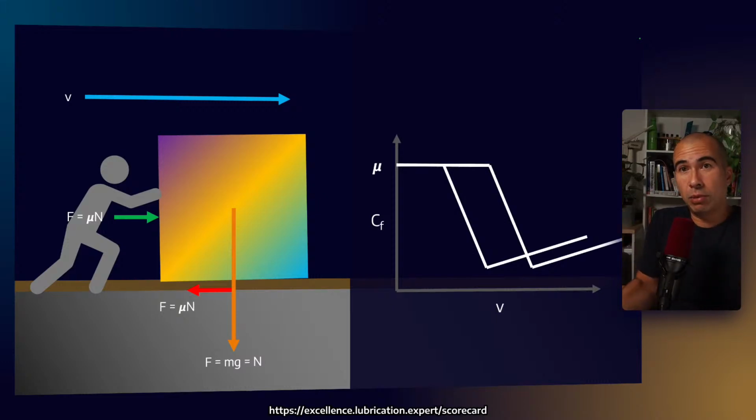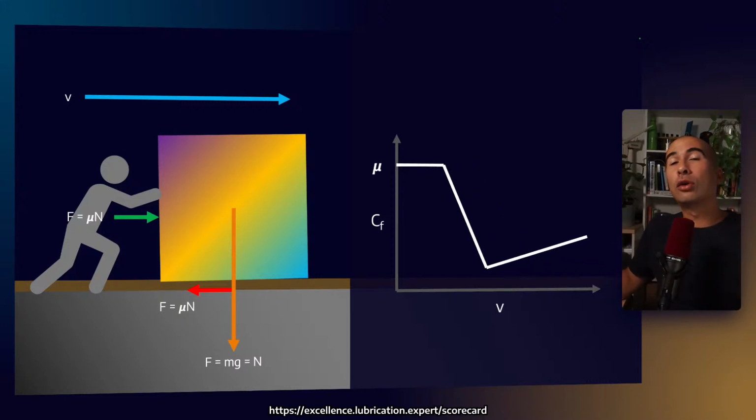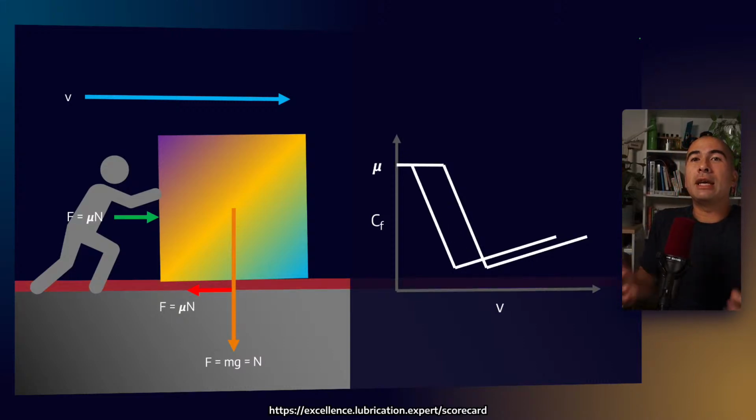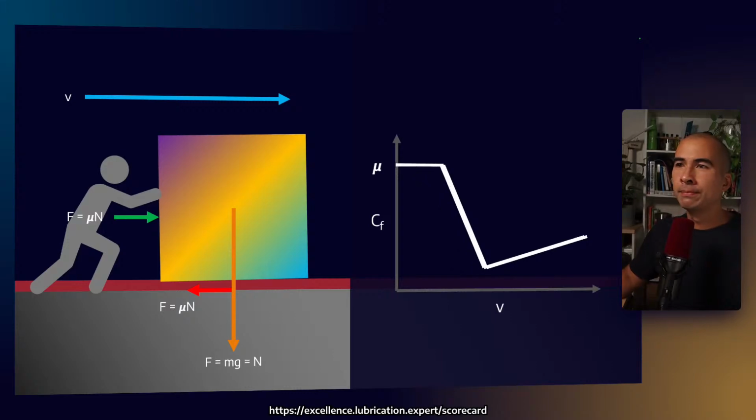And it makes sense. If the block is heavier, it takes more speed to get it to rise up into that lubricant. Similarly, what happens if we increase the viscosity of the oil that's on the floor? We might be able to instigate that lift earlier. So imagine if the floor was covered in honey versus it was covered in water, right? Honey is able to support more load than water is. And so we bring on that full film lubrication earlier. All right.